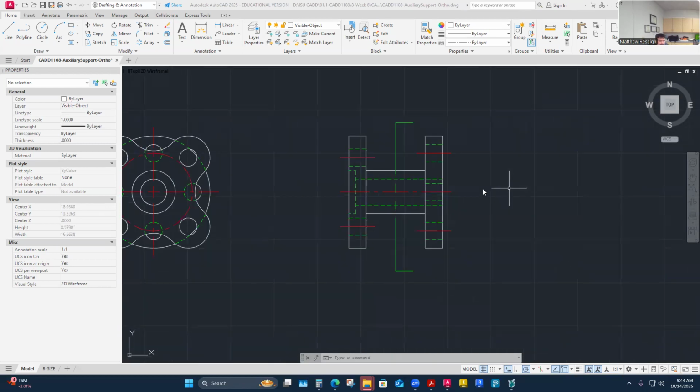But someone could say, well, because sectioning doesn't give me a lot of great detail, I might use the same method but instead of a cutting plane, we'd call it a viewing plane, and I would just place it out here away from any dimensioning, and I'd probably point those arrows the other way. If I mirrored this on the other side, it could become a viewing plane, and they look the same. Essentially, they have their arrows and the same kind of line type. I just call it a viewing plane rather than a cutting plane, and it shows that I'd be looking at the right side of it.